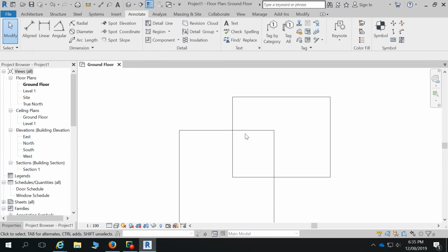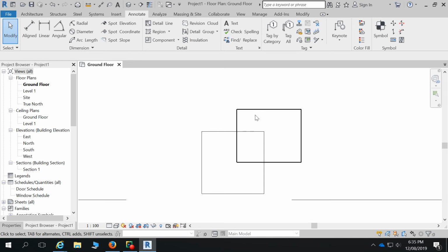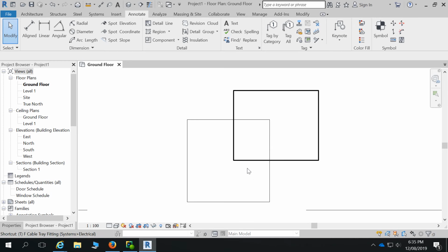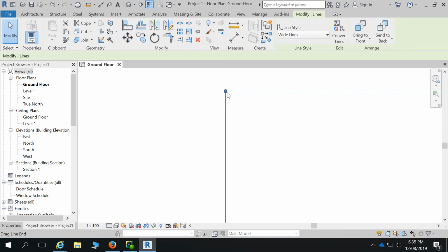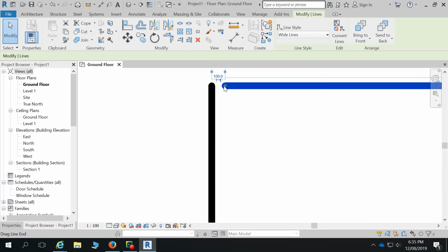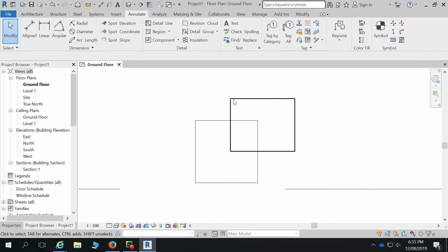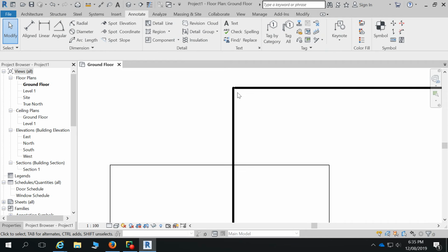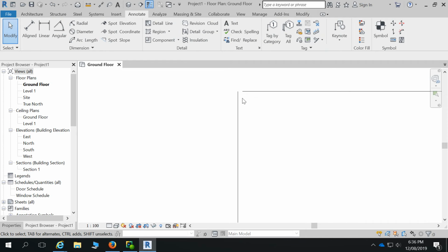So if I have thin lines on, they all look the same. If I toggle TL, the shortcut, you can now see the difference between those two line types. Okay, so one's thick line, thin line. Now, what we usually do is work in thin lines when we're modelling, because when I'm drawing with thicker lines, especially walls and things like that, it actually looks like they're touching on that corner there. If I change it to thin lines, it's very obvious that it's not connected. So that's what the thin line option on the screen is for, so that we can draw in a bit more detail. We haven't got these big thick things in front of corners and that sort of thing. So it's just a visual aid on the screen.